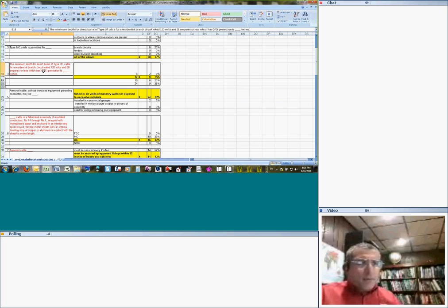This one confused you guys. If you have a UF cable in a residential application, branch circuit, 120 volt, 20 amp, GFCI protected, you don't need more than 12 inches. That probably confused some of you.